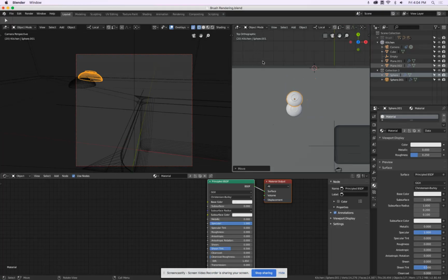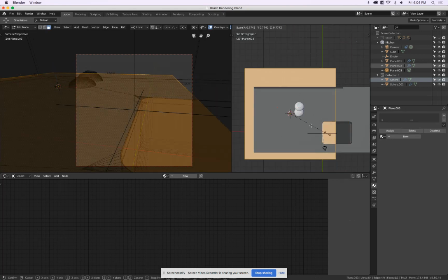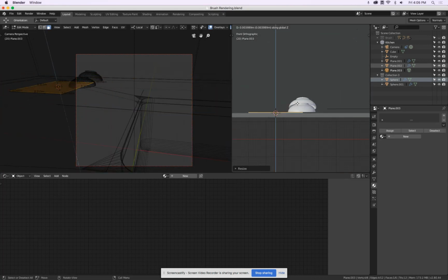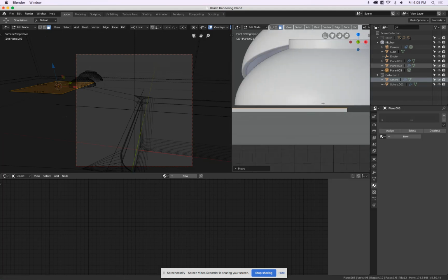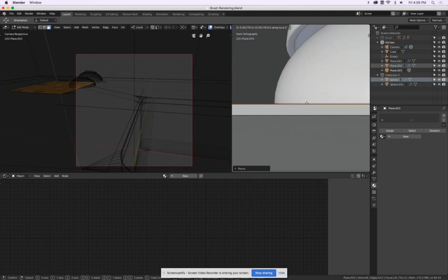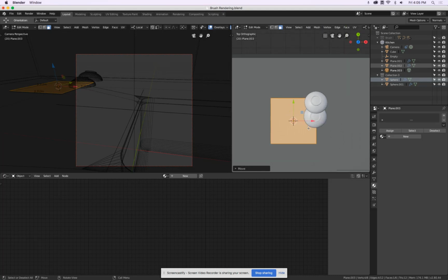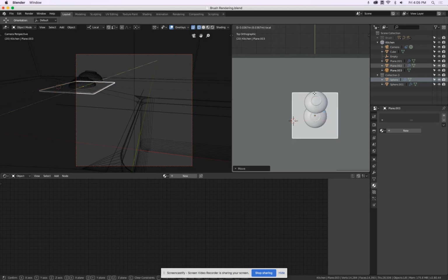So click, click, click. I just set the 3D cursor, make myself a plane, in edit mode edit it, G and Z, G and Z, G and Z, hold Control, or G and Z, I just eyeball it there. Very good. Move it to there and there.